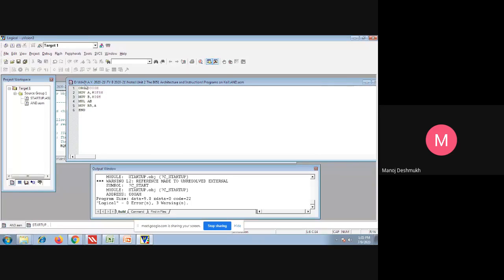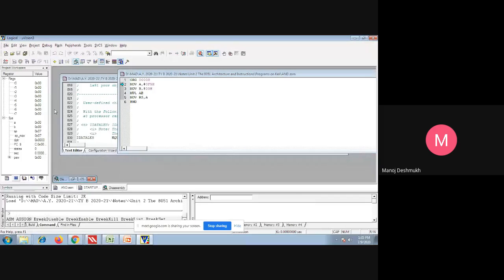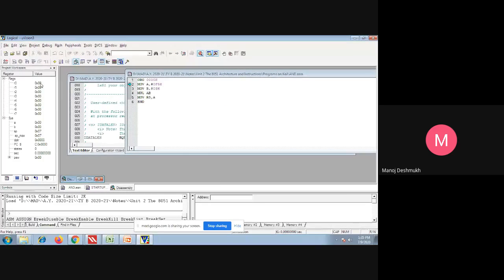So after this, we will start execution, debug. Initial contents, whether it is seen to you: R0, R1, R2, up to R7, and then SFRs, A, B, stack pointer, and maximum position of stack pointer, program counter, and states. After that, the PSW register is there. Initially it is 00. When some operation is performed and the result is stored in the accumulator, that is, on execution of an instruction, the content of PSW may change. We will see. So we will go step by step execution.